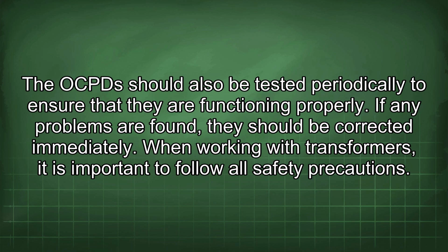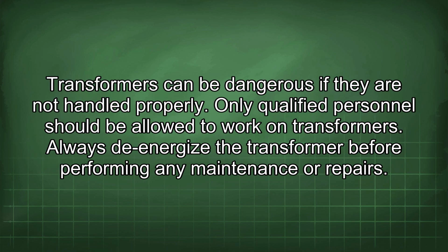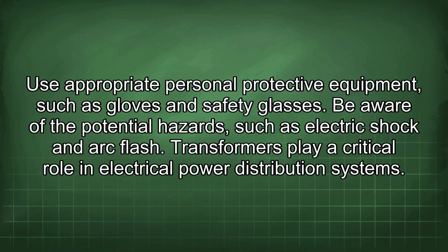When working with transformers, it is important to follow all safety precautions. Transformers can be dangerous if they are not handled properly. Only qualified personnel should be allowed to work on transformers. Always de-energize the transformer before performing any maintenance or repairs. Use appropriate personal protective equipment, such as gloves and safety glasses. Be aware of the potential hazards such as electric shock and arc flash.